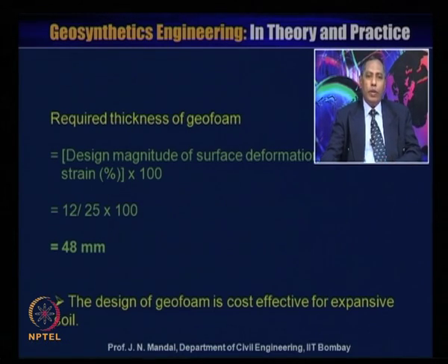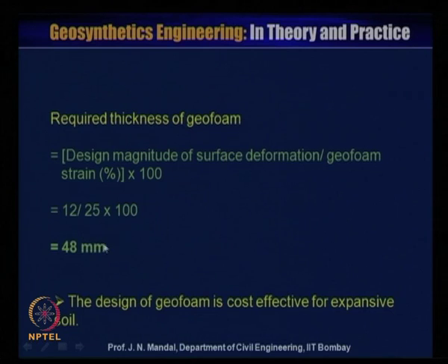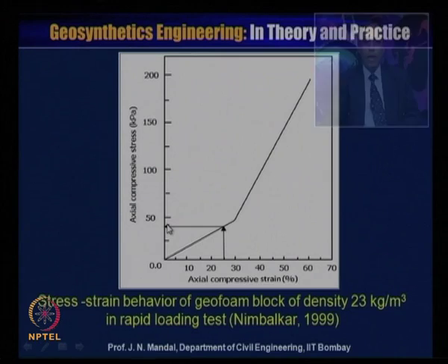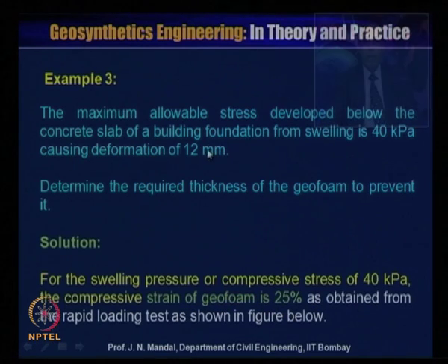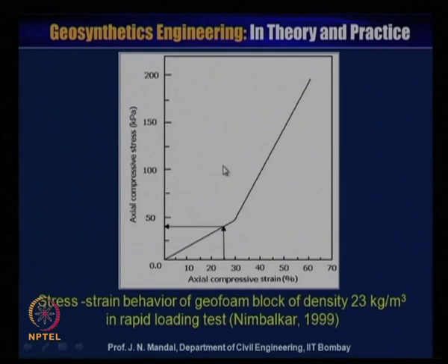So you know the design magnitude of the surface deformation is 12, which is given in the problem: for this swelling pressure of 40 kilopascal, the deformation is 12 millimeter.